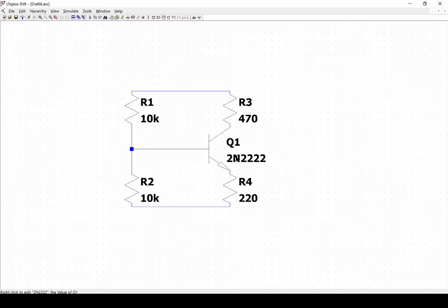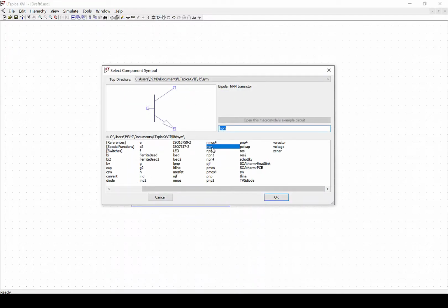So now we have the schematic of the circuit, but of course, as every circuit, there is something missing, right? And we need to add a power supply if you want to supply a certain voltage and current to the circuit for the circuit to operate. So once again, in order to add a power supply, we will click here on component, and we will look for this voltage. You see here, you have already the symbol of the power supply, voltage supply. So if I click here, of course, I would have also a current generator here if I wanted to, but in our case, we want to apply a voltage.